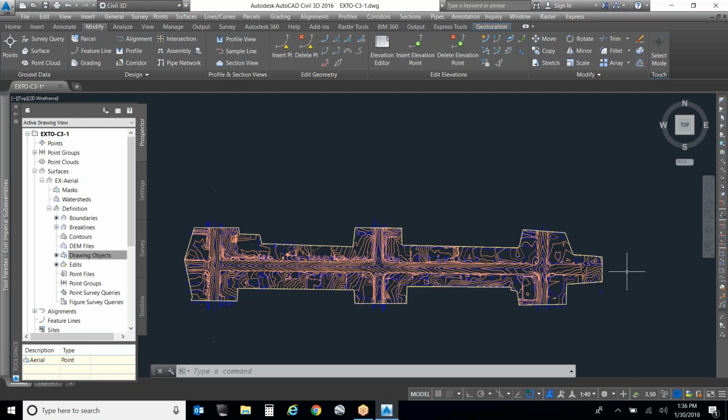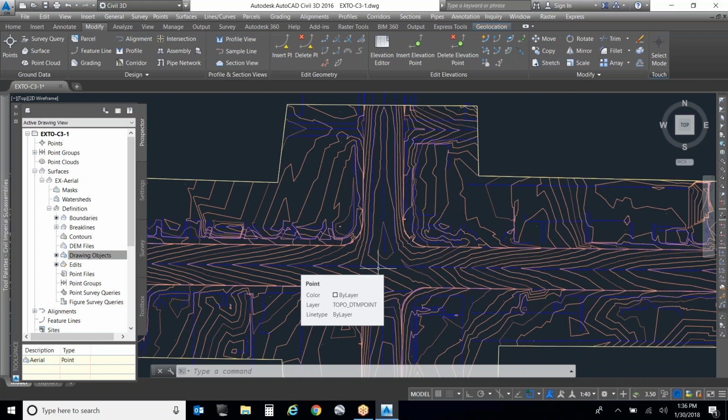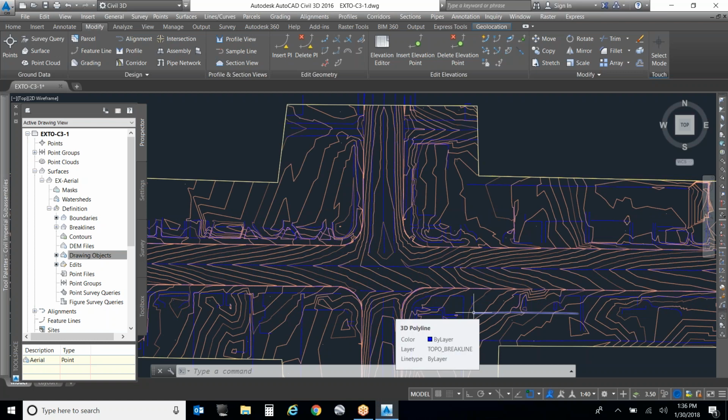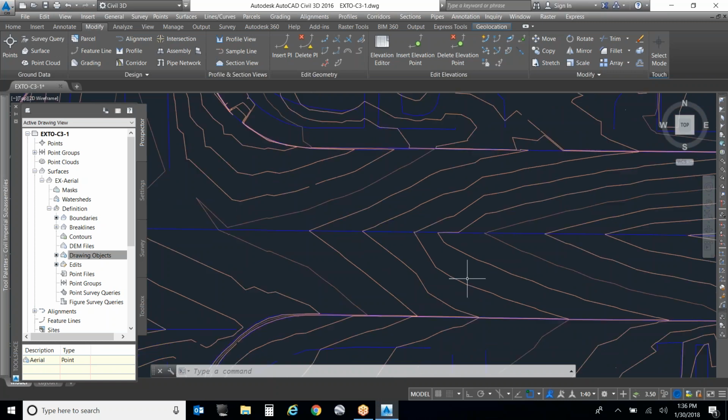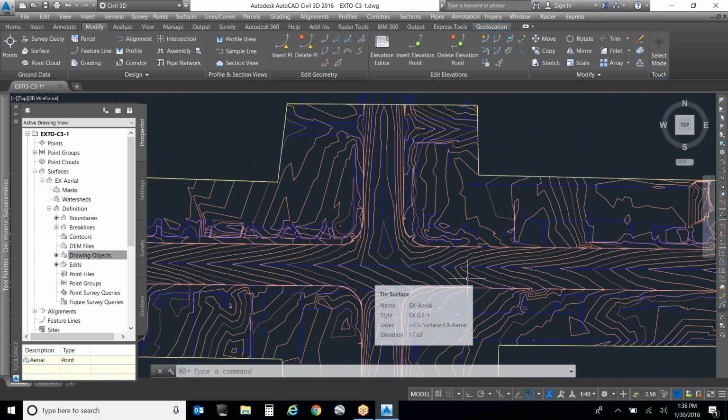Okay, I guess that makes sense. It would also be a very clear way of seeing which pipe is potholed as well, because you have a point in your profile where you have pothole information. When you have your pothole, you have your elevation where you find it, but if you're doing your pipe networks, you're still going off of a surface, right? So when you start editing those pipes,